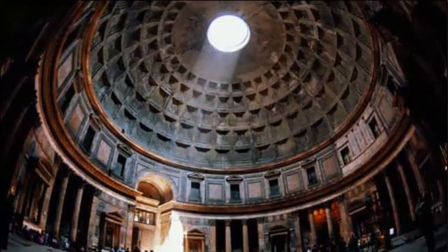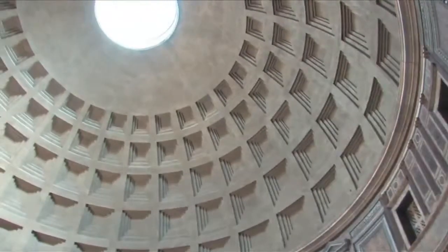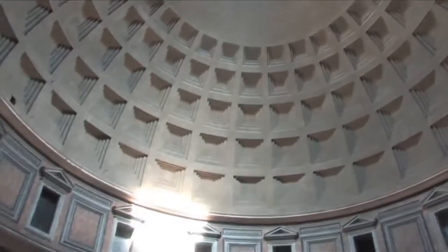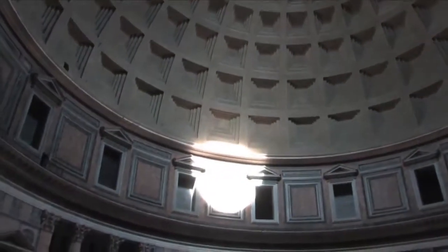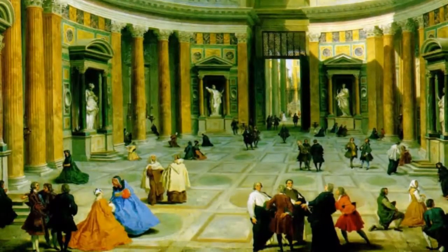The oculus at the top that we had looked at before really is a way of relieving some of the stress, allowing natural light to come in and smoke to come out. But students always ask me, so rain gets in, right? And birds and stuff. Yeah, well, rain does. And so what they did with the floor is there's actually a slope to the floor and a series of drains that run underneath it. And since the floor is basically made out of stone, the surfaces would not have been hurt or damaged in any way.